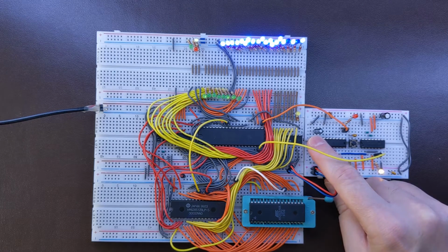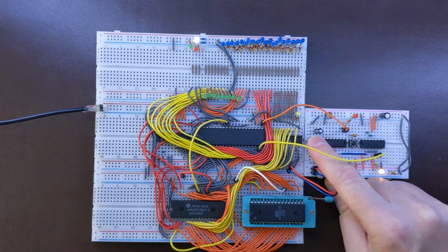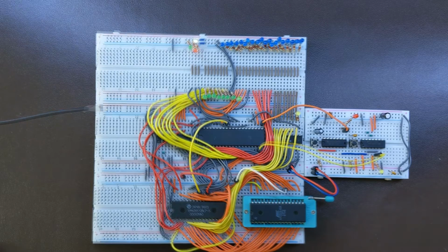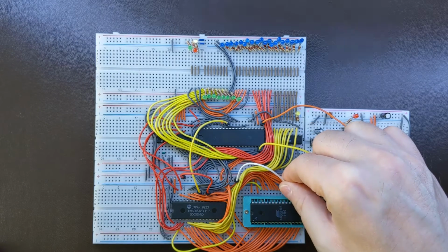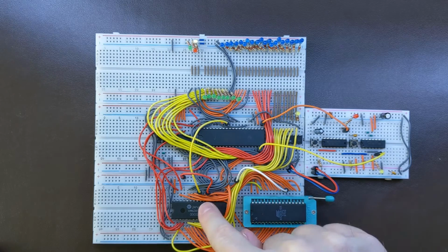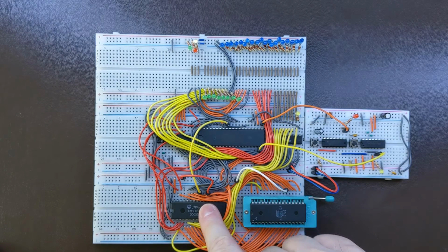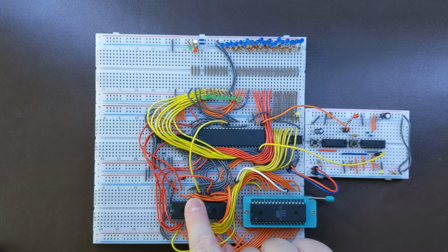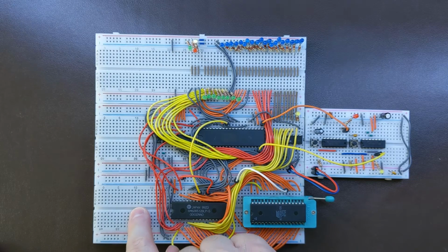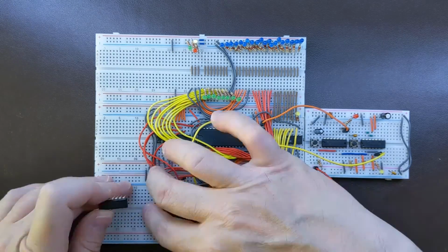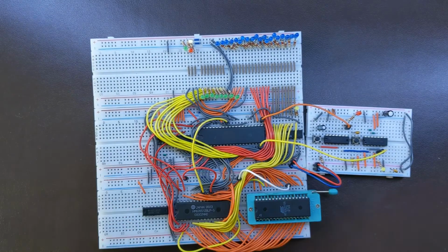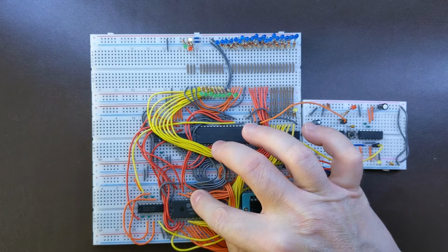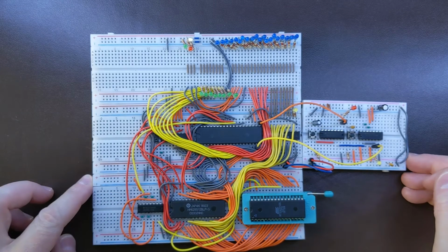So it looks like everything is okay. Our program from the previous video still is working. What we now need to do is to connect chip enable of the flash and chip enable of the RAM memory to our contraption using 74HCT00. We will find out very soon if our computer, together with freshly added RAM memory, works as expected when we start it in just a few minutes.